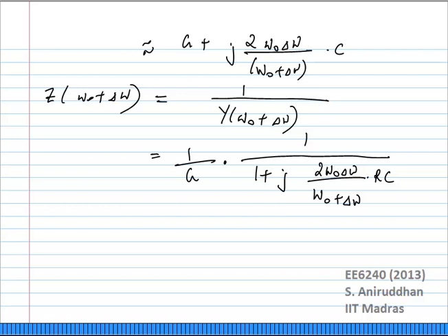The other thing we are going to use is the representation of the quality factor of the tank. The reason is this. We know that as the quality factor of the tank increases, the filtering ability of the tank for noise also increases. Therefore, the phase noise should get better and better, right?